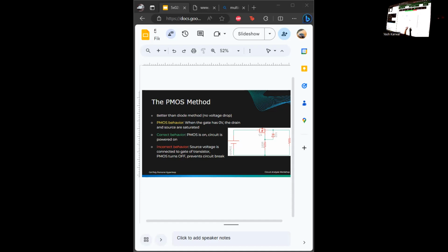Wait, why is it not? Well, normally, so you're going positive into this gate, and then you have the negatives. Oh, no, sorry, ignore me. Not that. You have -5 volts going into this one, right? And remember how I said that the voltage at the gate has to be the lowest voltage. But right now, the lowest voltage we have is -5, right? So that's why it's not going through, because 0 volts is larger than -5, right?